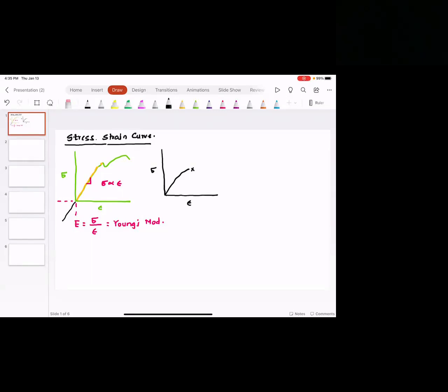In other words, when we plot stress strain curve, we have a metal piece that we pull on both sides. The material stretches. There is tensile stress, there is elongation, and finally we get this nice curve. But have you seen an experiment where something is compressed? No. Why? Because when you compress, the most significant failure that happens is buckling.